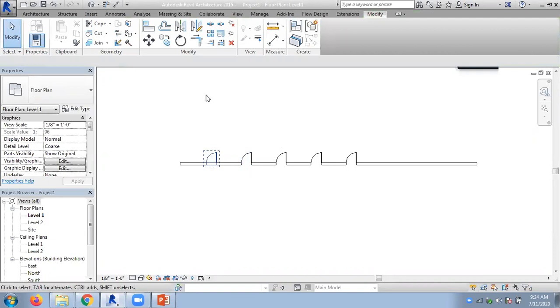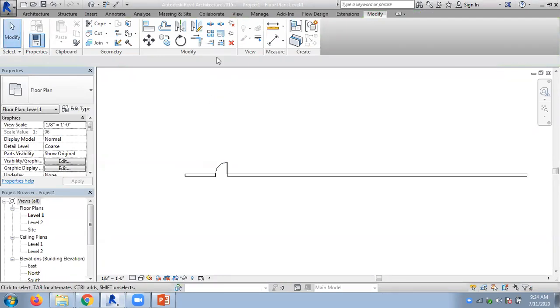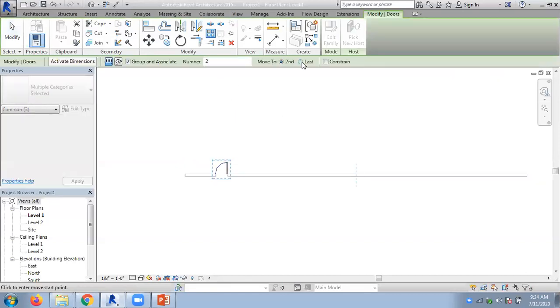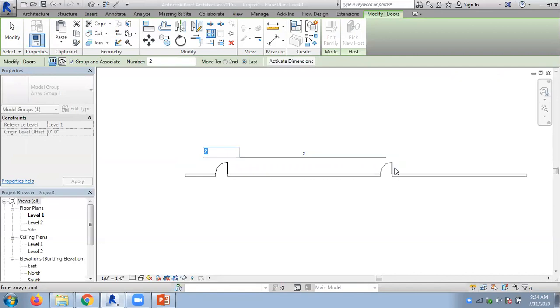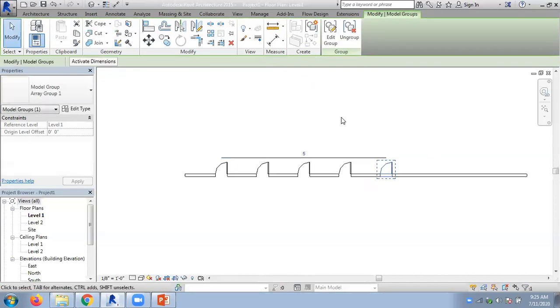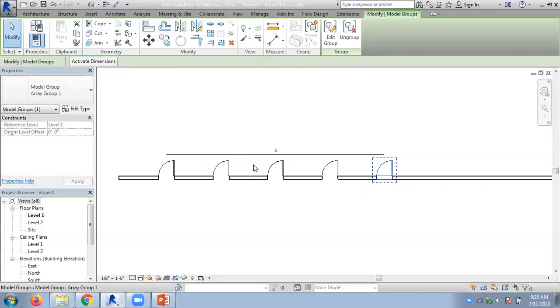So we will look at the last method now. So you have this method, last method. Last method is if you know the gap between the first one and the last one. Sometimes the gap is not a full number. Say 41. So I have a gap from the first one to the last one of 41 inches, 41 feet. I want to have 5 rows in between them. So this method is somewhat easy because people will think in this pattern.